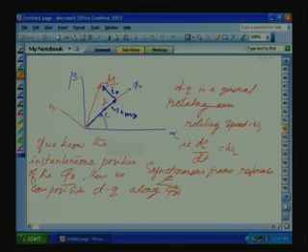So, what we require here is the instantaneous position of the psi r. Now let us derive the stationary reference frame model alpha beta with respect to a general rotating reference frame dq, so that we can appropriately place the speed of the dq.